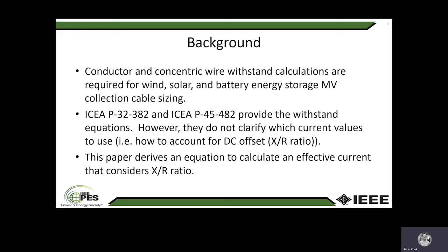Now, one shortfall of these standards is they don't really clarify what fault current to plug in. For example, your power system software gives you symmetrical momentary, half cycle asymmetric, half cycle peak. What do we plug in here?